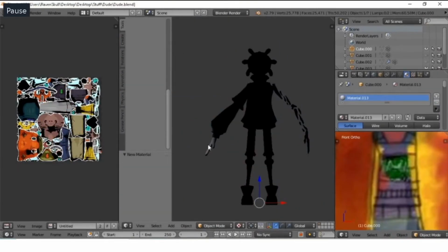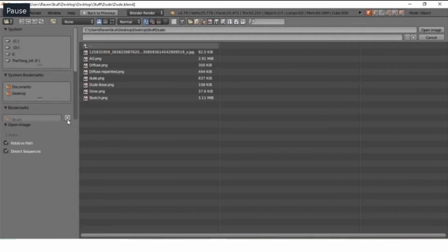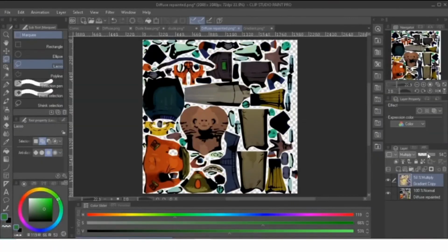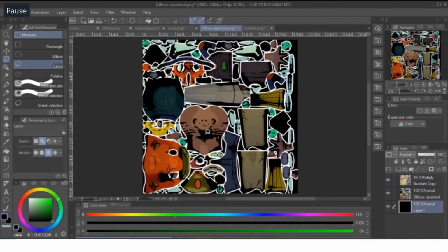So in here I took out the model and I duplicated it, and I applied an unwrap process to it, but based on the view, and I applied a gradient map to it, and I took that model and I texture bake. So I select the gradient map model with the messed up UV, sorry, and select the mesh that has the texture, and I bake.